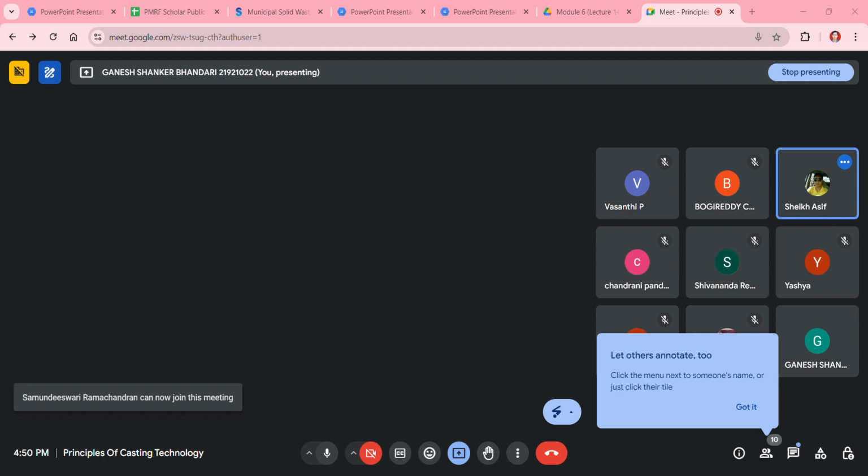As a function of round trip haul distance, because we are not talking about haul distance here as a particular value. Okay, we will talk about haul distance as x. Here x is this haul distance. So we have to calculate according to the round trip haul distance function. If you have that haul distance, you can calculate the entire time period for the week.